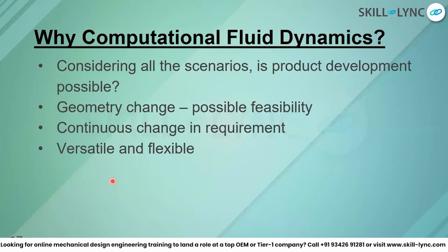If the first time you did the test and you say okay, results are okay, no, have you done the validation of your own test? If you perform the test at least 3 to 4 times, where is the variation happening, and how much variation do you see? Some of the parameters will not change out of the tolerance zone. It will be, for example, ±5, but it should be in that zone. If they are changing drastically, there is some issue in the test. There might be some issue in the machinery, probes, or maybe the digital meters you have kept.